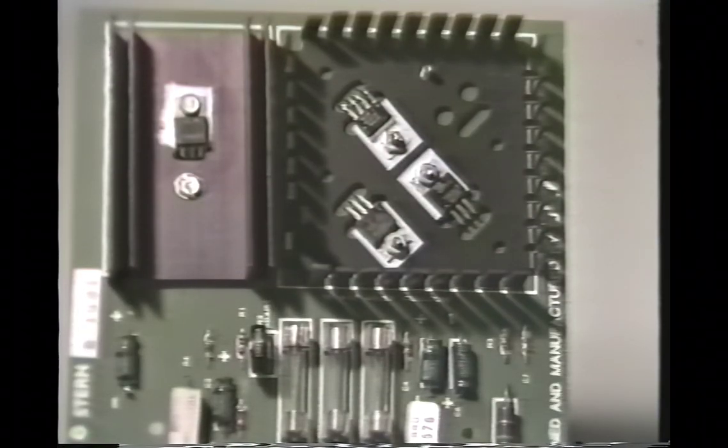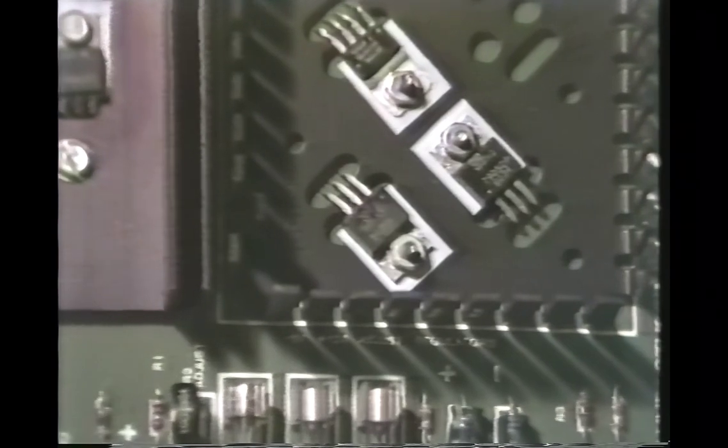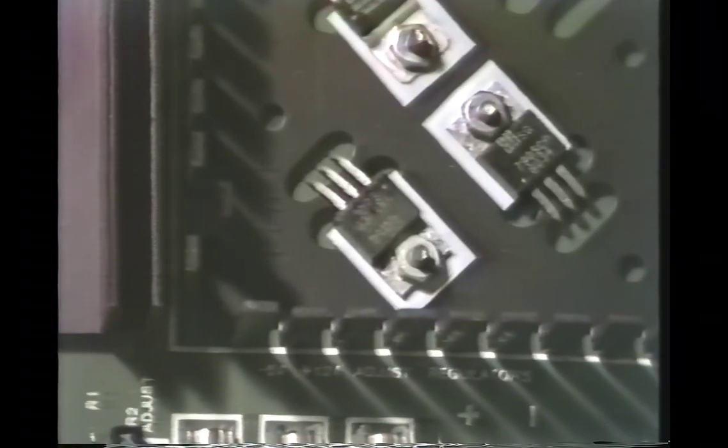There's another type of regulator that you'll often see used in place of the 78 series regulators. And these are the LM340T series. As before, the voltage is indicated by the number following the T. Thus, the LM340T-5 is a plus 5 volt regulator, and so on. Both parts are interchangeable, and you may even see a single device with both the 78 series and the LM340 series number printed right on it. This Stern power supply is typical of most that use 3-terminal regulators. And here we see 3 regulators mounted to this black aluminum heat sink.